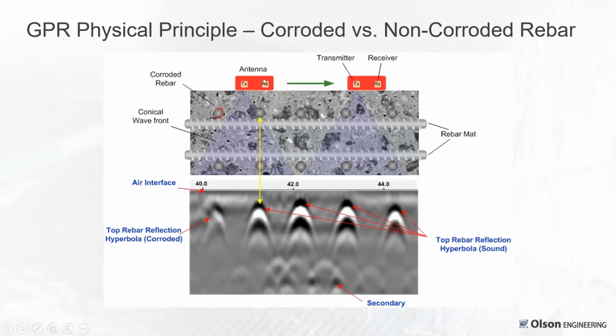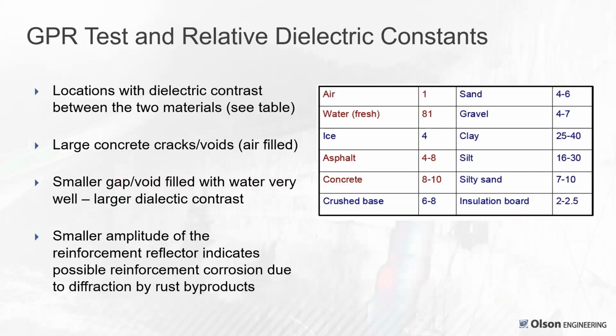And here the antenna is moving along with a transmitter and a receiver. You're actually picking up with that geometry, these so-called bow tie antennas, you're crossing over these rebars. So you're going over them. You can see a little bit of banding here that could be attributed to if you're right over the longitudinal rebar, but that doesn't show up as well as going across it for mapping rebar. So you would scan 2 directions if you wanted to see the other steel better.